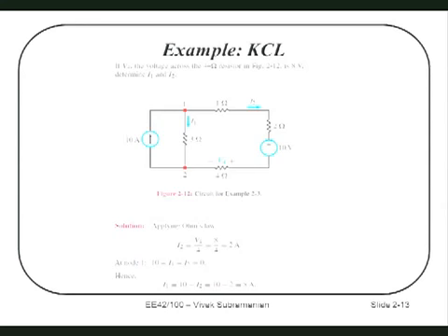Second part, I'm going to do the math at this node, node 1. Is that node an ordinary node or an extraordinary node? Extraordinary. How do you know it? 3 or more branches. It has 1, 2, 3 branches. So it's an extraordinary node. 3 branches. What does Kirchhoff's law tell us, the current law? Sum of all the currents going in has to be 0.